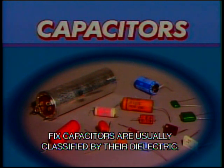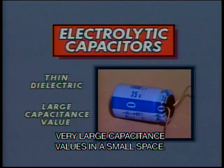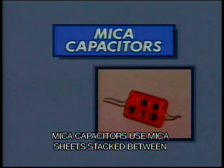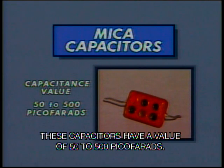Fixed capacitors are usually classified by their dielectric. Electrolytic capacitors use a very thin oxide film as the dielectric and have very large capacitance values in a small space. Mica capacitors use mica sheets stacked between tinfoil sections which conduct the current. These capacitors have a value of 50 to 500 picofarads.